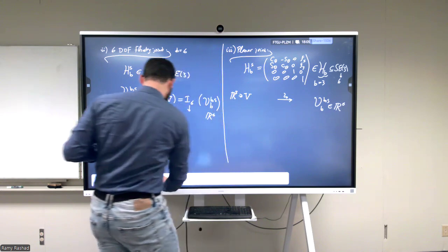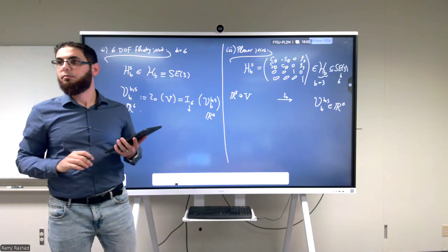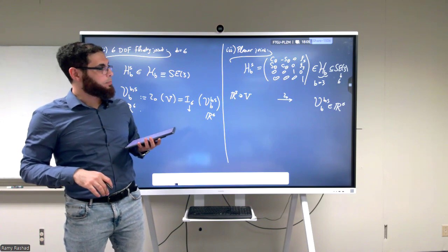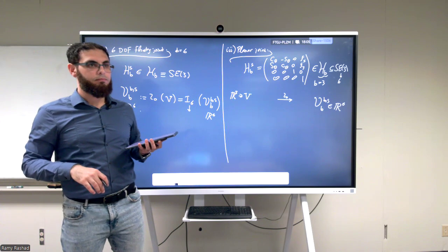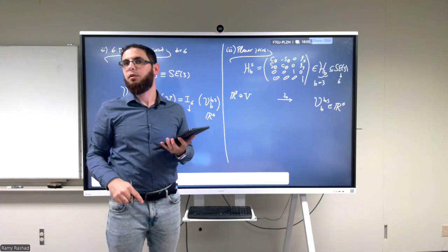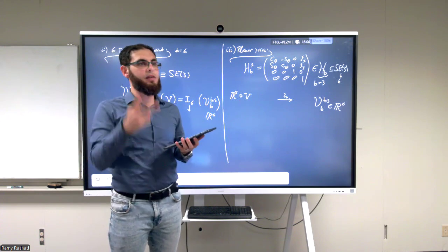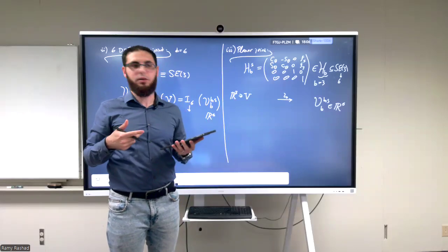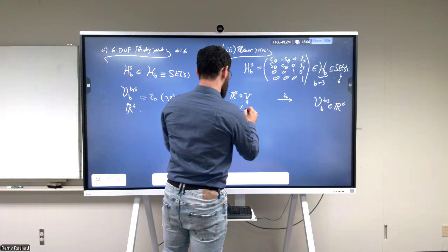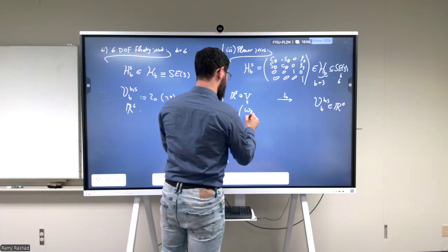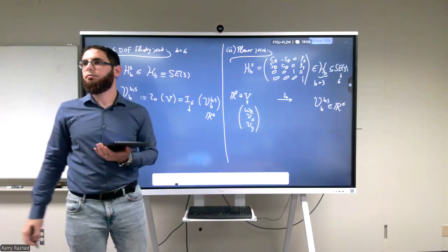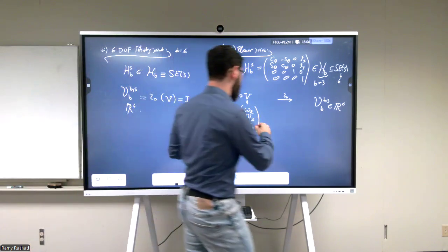Wouldn't it be the Jacobian in the case of 1 degree of freedom, putting the F and theta dot? No. Okay, so what do you think the variable V is? 3 variables. You need 3 variables to describe the velocity, right? I'm going to choose them to be omega around the Z, velocity in the X, and velocity in the Y. And I'm going to map them by this map.